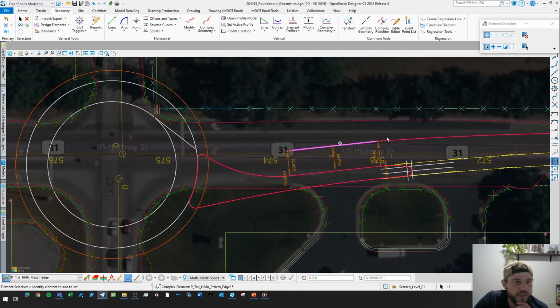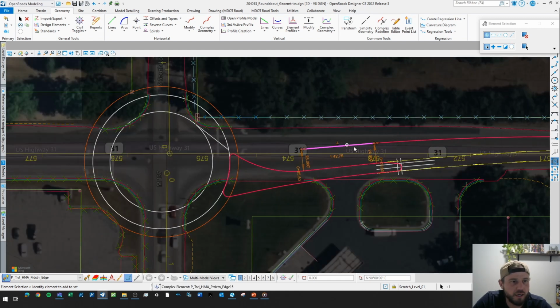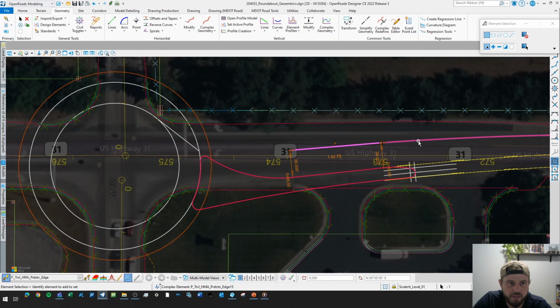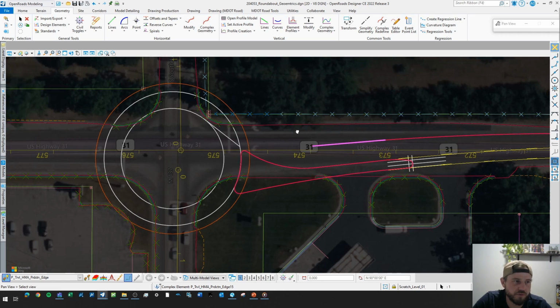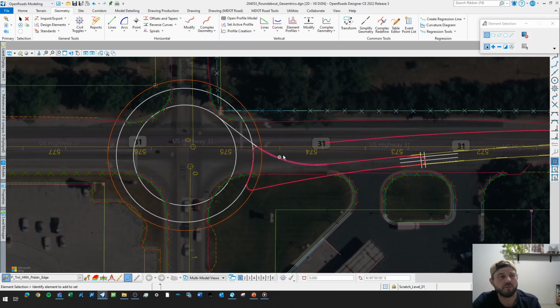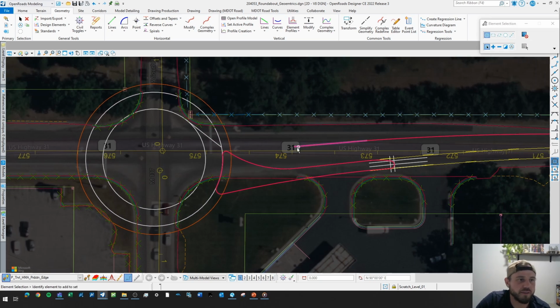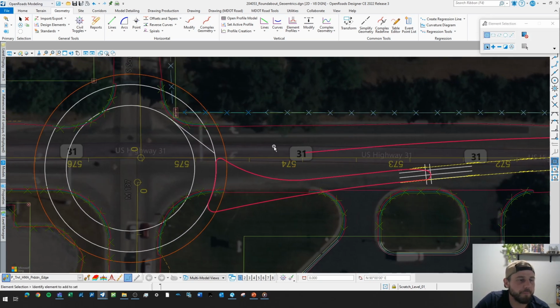Here I think we're going to want to keep on expanding out a little bit. If we keep this ratio the same as this ratio, then ideally we can, but we do want about 30 feet, I think, for an entrance for two. And the main thing there is we have a truck apron in between, kind of a chevron, where trucks get to use a little bit of that extra lane.